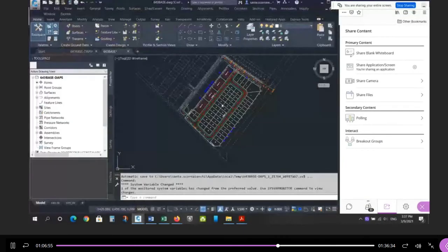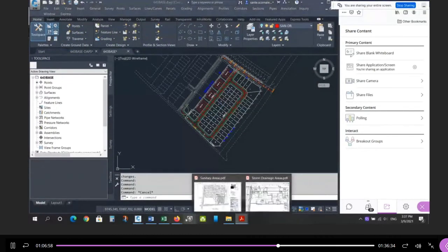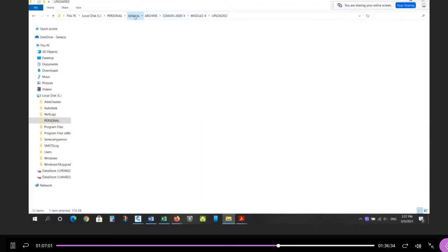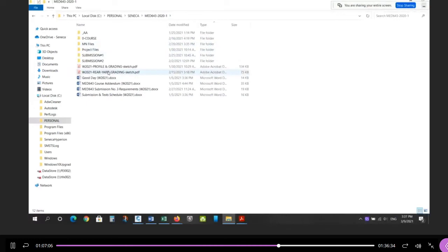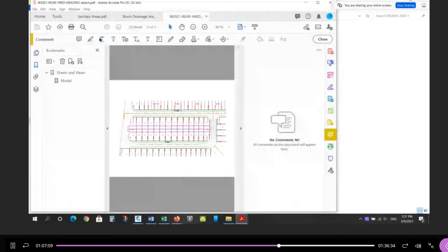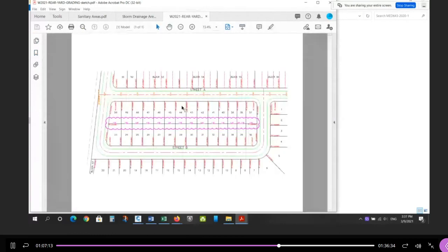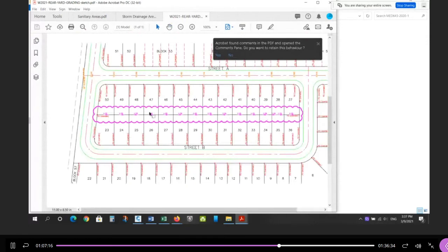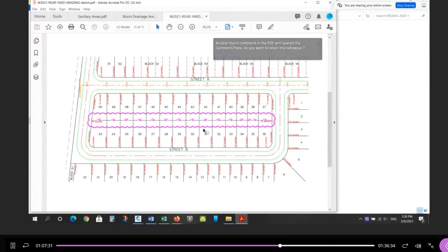Right, let me just share this again. So when you're looking at the backyard elevations, what's happening back here based on these graphics, let me just show this again. Yeah, so based on this, I told you what to do back here. And again, it's a guide, right? I told you what the relationship between the points at the back is. You can't do this lot grading at the back until your corridor elevations at each end are correct, or close to what I've got. And then you can do all your elevations along the backyards, and then you've got your front and back to do, which shouldn't take too long. Like I said, most of the design is simple split. There might be a back split over here somewhere, maybe between 5 and 6, but that's the only place I anticipate a problem.